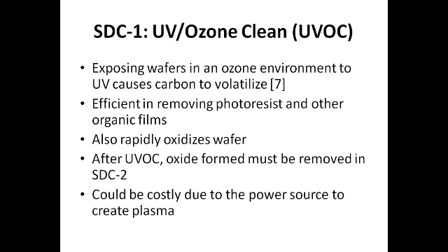But in the meantime, it also rapidly oxidizes the wafer. So after this process, dry hydrogen fluoride must be used to remove oxide, just like in RCA clean. The process could be costly due to the power source, which is needed to create plasma.